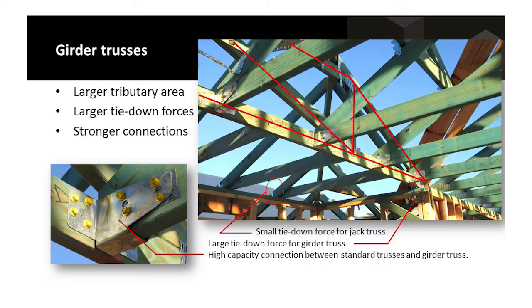I've mentioned girder trusses before. Girder trusses pick up the load of other trusses. So here is a girder truss highlighted in red with other trusses coming in and sitting in fairly massive boots. They transfer load into that girder truss.